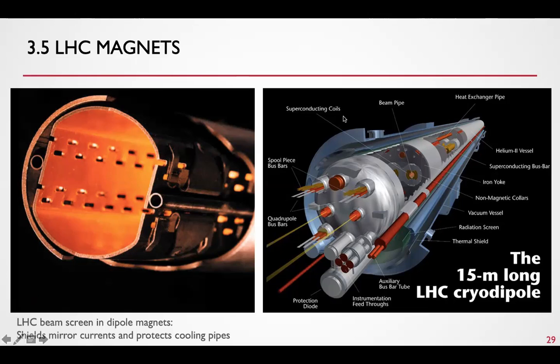And this evaporating helium needs to pass through valves. You need to remove it again because you cannot build up the pressure. And that's what failed in 2008. I think it was 2008. So there was one problem at the LHC startup where we had a quench at one of these junctions, and the evaporating helium could not be released through the valve, which was too small, it was under-dimensioned.